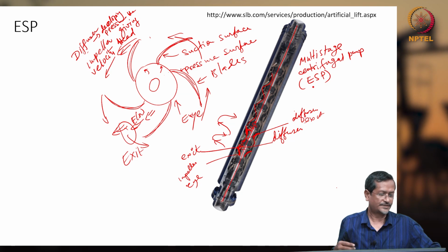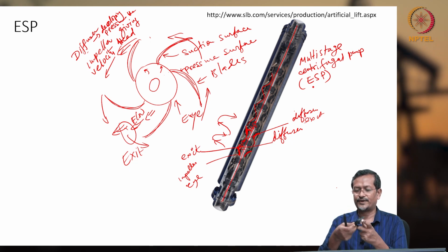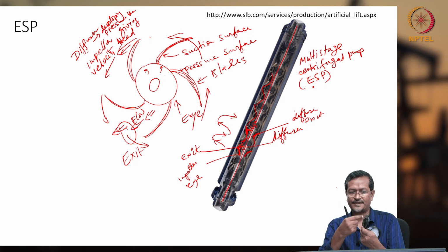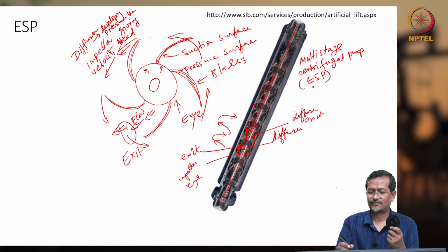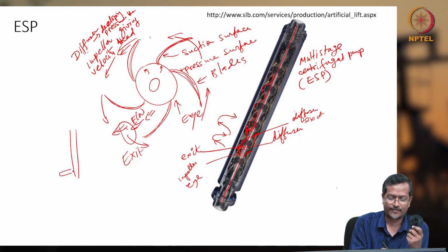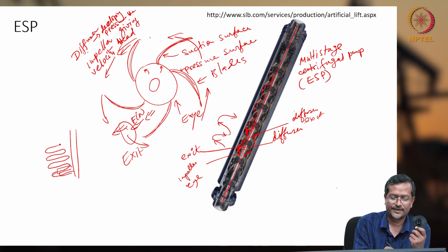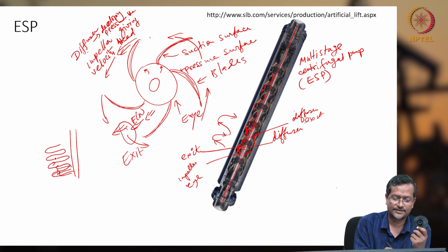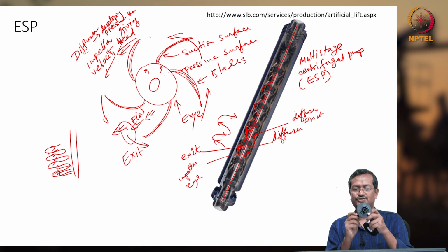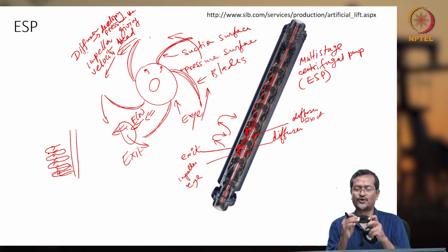Okay, now let's see one impeller. This is one very thin plastic-made impeller. Fluid is entering the impeller inlet, going through the channel, and going out, so it is the exit. Impeller entry, exit. If I have a radial flow impeller, then I have the shaft, and a radial flow impeller means the impeller will make the flow path like this. Then the diffuser will be there, diffuser entry, impeller entry. So fluid will be moving like this. Again it is not two-dimensional. If I have one shaft here, it will actually be rotating. Impellers are curved, but for representation purposes I am drawing a two-dimensional figure.